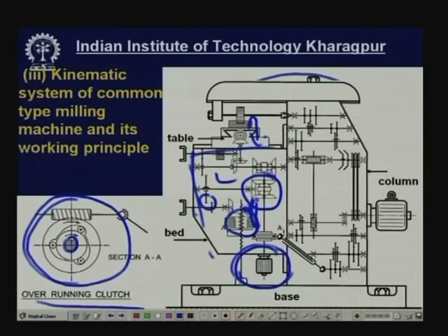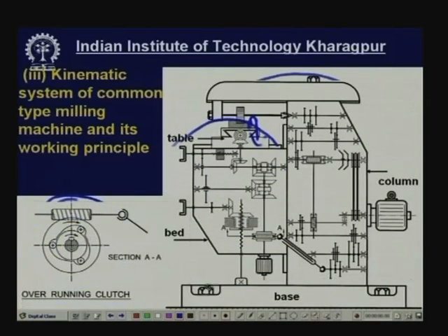This is the shaft of the motor, and when this worm rotates, it rotates the worm wheel. When that worm wheel rotates, these 3 rollers get jammed into this space, a friction jam, and then this disc is rotated, transmitting motion to the shaft. Okay. Now, when it is not required, this motor is operated at high speed, this will rotate directly, and that will help get all the feed motions rapidly, all right. This gives you the quick traverse motion, this one and this overrunning clutch together.